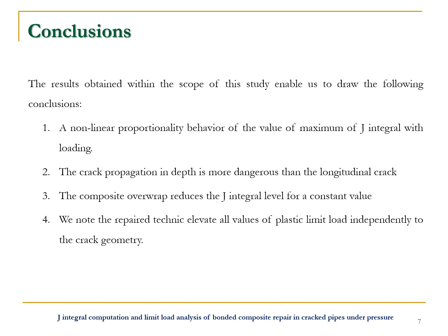Finally, the results obtained within the scope of this study enable us to draw the following conclusions. Firstly, a nonlinear proportionality behavior of the value of maximum of J-integral with the loading. The crack propagation in depth is more dangerous than the longitudinal crack. The composite overlap reduces the J-integral level for a constant value. We note finally, the repair technique elevates the values of plastic limit load independently of the crack geometry.